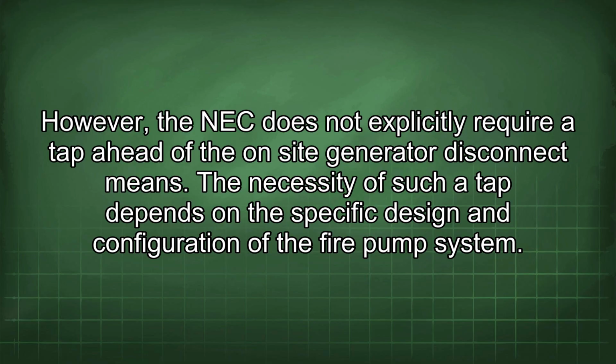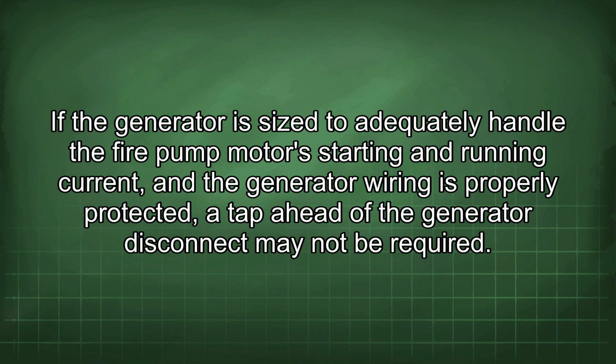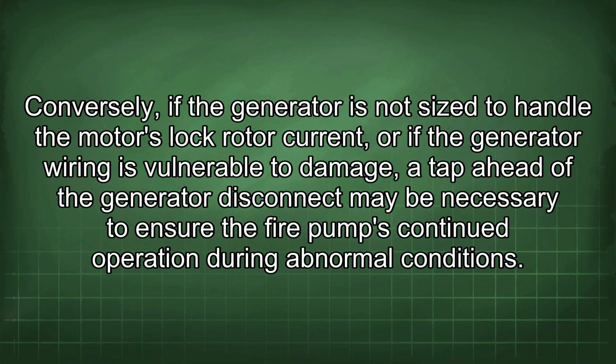However, the NEC does not explicitly require a tap ahead of the on-site generator disconnect means. The necessity of such a tap depends on the specific design and configuration of the fire pump system. If the generator is sized to adequately handle the fire pump motor's starting and running current, and the generator wiring is properly protected, a tap ahead of the generator disconnect may not be required. Conversely, if the generator is not sized to handle the motor's lock rotor current, or if the generator wiring is vulnerable to damage, a tap ahead of the generator disconnect may be necessary to ensure the fire pump's continued operation